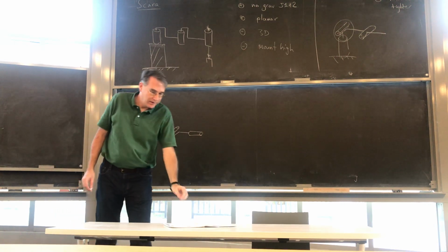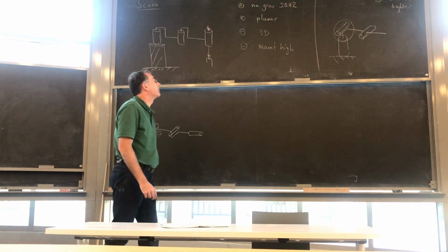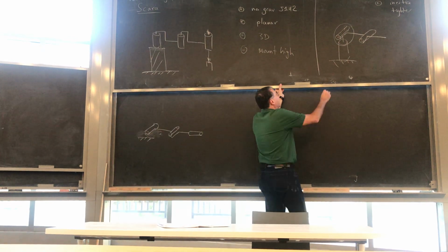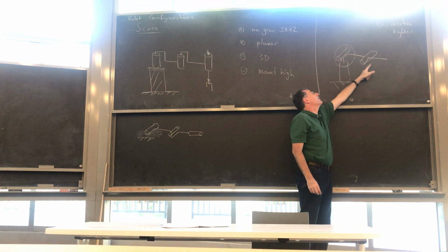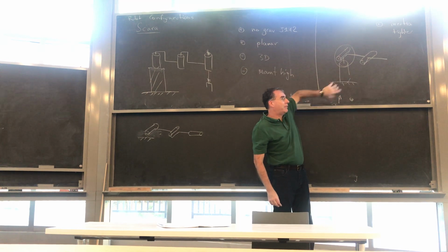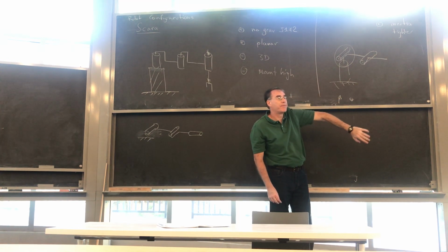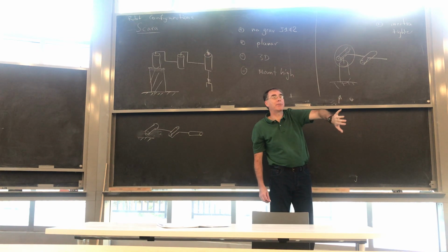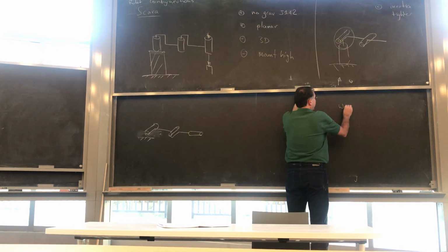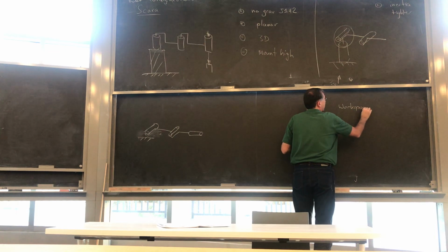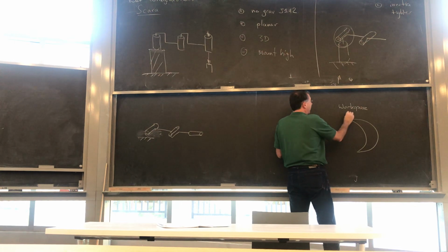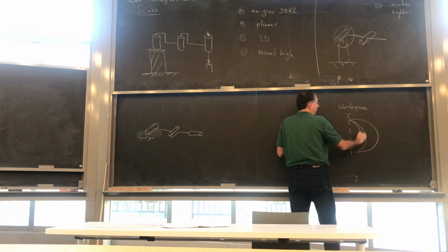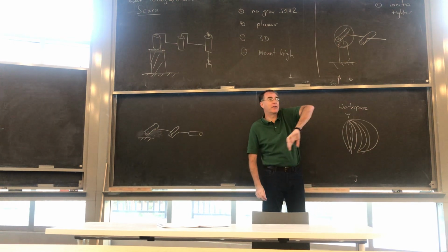The only slight thought I'll add to that is if I look at this guy, if you think about what it's doing, if I come from the outside in, right? The outside is sweeping in this plane, and then the base motor is rotating that plane around. So if I look at my workspace, do you agree that basically the outer joints do this half moon, and then the base joint causes this all to rotate around in this fashion?